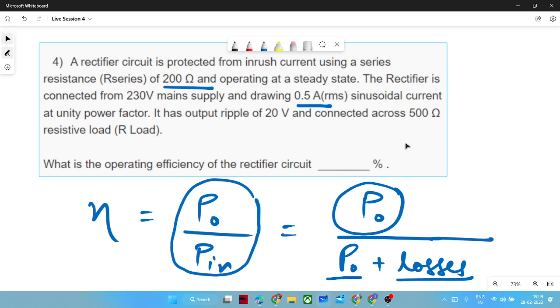Yes, 325 at the output. Not 325, it would be... The 325 minimum voltage you are talking about, right? 325 minus 20 would be the minimum voltage. Yes, so that would be the ripple there. And even now, in the present case also, 20 volt will be the ripple.